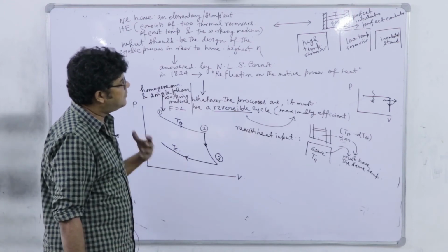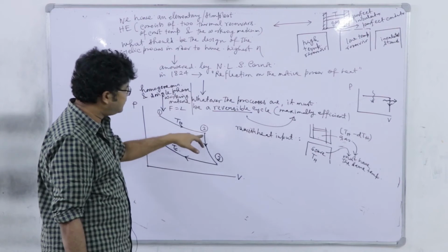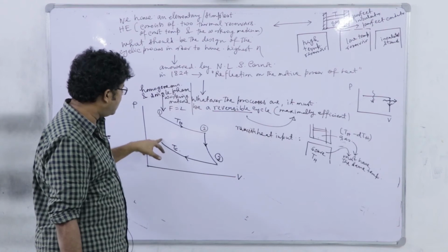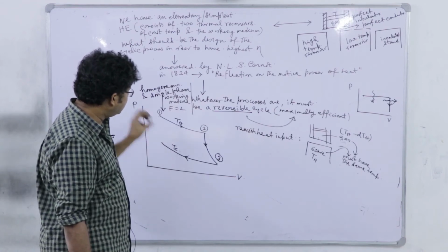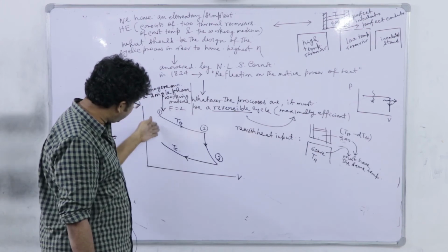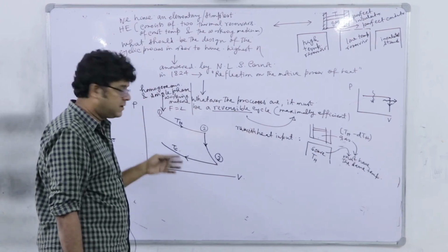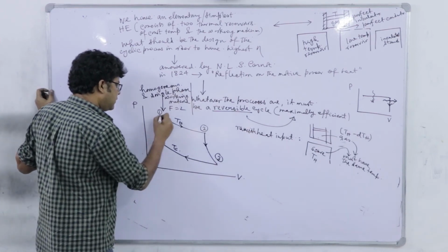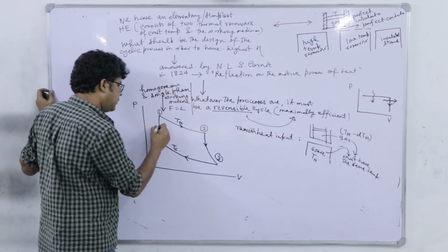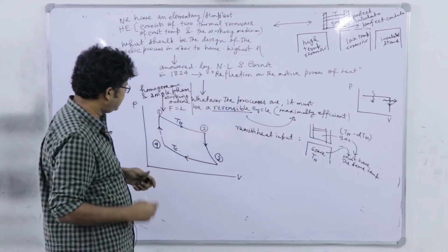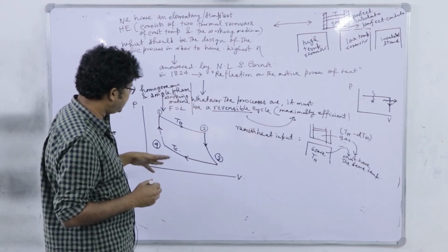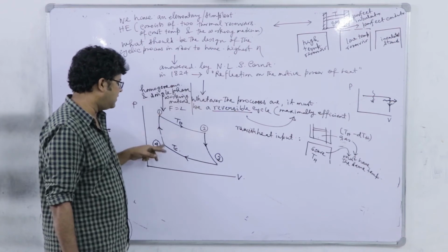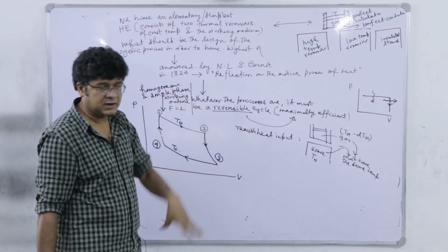So, if I have to implement reversibility with these limited utilities, I have to go first for an isothermal expansion, then an adiabatic expansion, then isothermal compression, and we will continue it to some state 4, such that if I draw an adiabatic line through 1, it must pass through the point 4, right. So this is point 4, and we have to regain this state. So definitely we have to regain the state, and regaining it is only possible by isothermal compression.